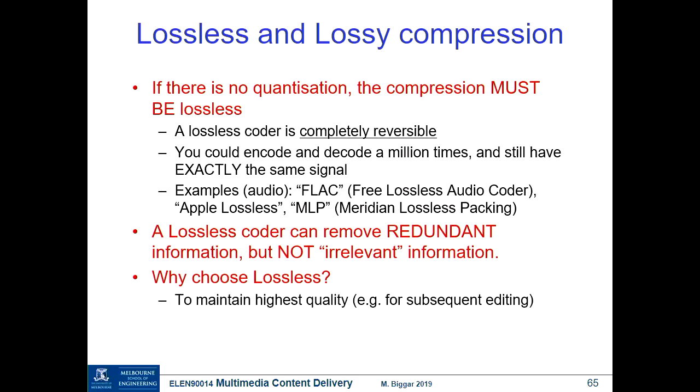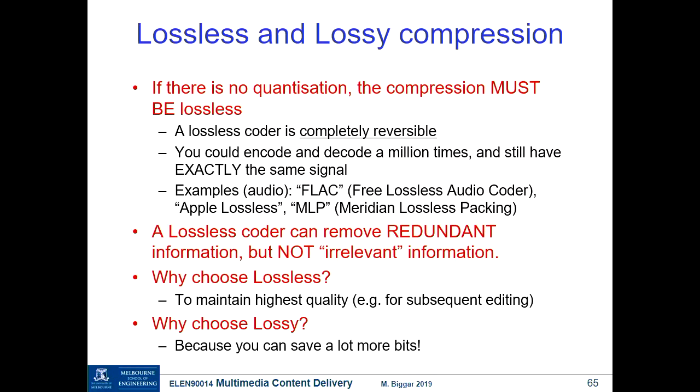I wasn't supposed to give you the answer immediately, but you presumably realise that we would choose lossless coding when we want to maintain very high quality, either because we are audiophiles and have a very high quality, very expensive audio amplifier and loudspeaker system, and we believe that we need that highest quality, or perhaps we want to maintain that highest quality because we could subsequently process it, for instance doing some editing, so we would maintain lossless coding in that case. When would we choose lossy coding then? Yeah, for final distribution. So when the distortion we introduce will be acceptable in the application, and we want to save bits basically. You can save a lot more bits once you're prepared to sacrifice some of this data.